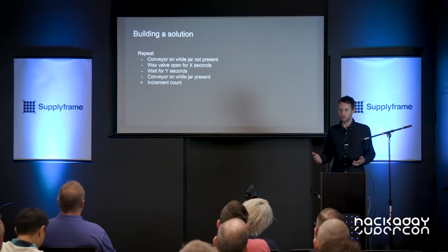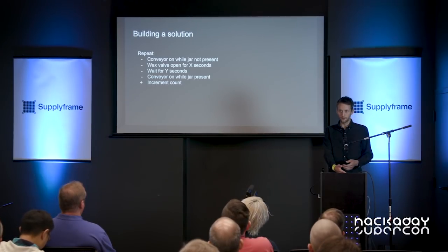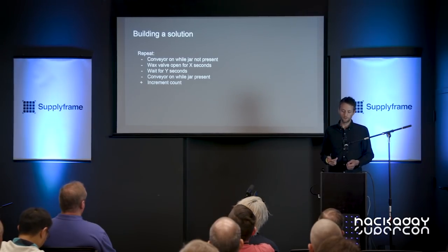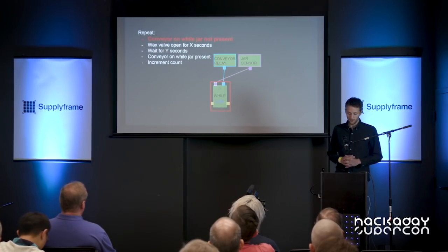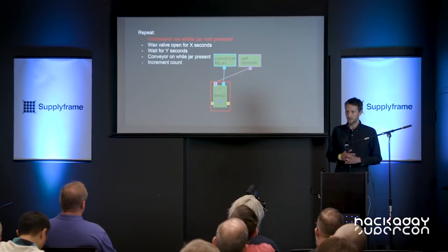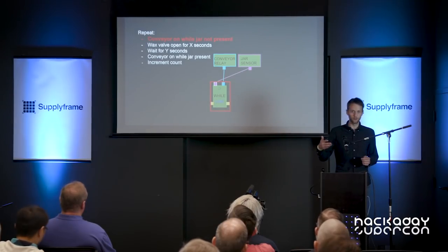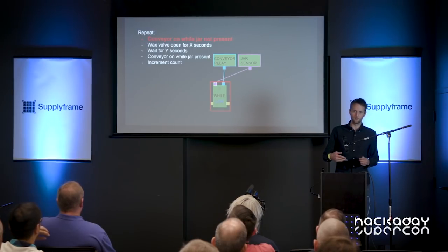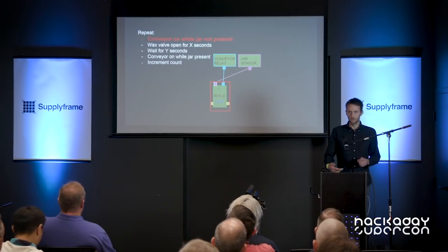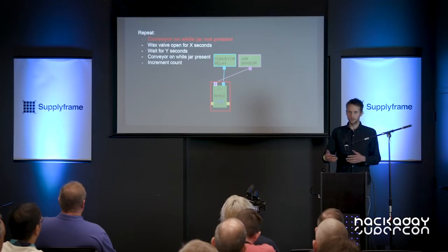So now that we have all these pieces, we can actually assemble them and build this solution. We can see what that would look like. This is that machine algorithm from the earlier slide. I've just copied it here. Add an extra line to increment the count as an excuse to use the counter block. So first step, we want to move the jars forward. So we use a while brick. We connect the active output to the conveyor relay and have the jar sensor to the input and select that block. We select the condition to be low so that the relay is going to be on while there's nothing blocking the jar sensor.